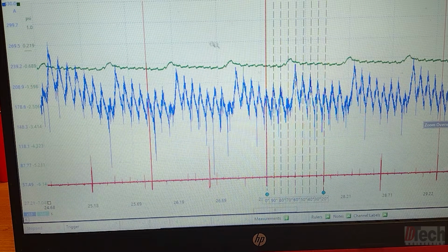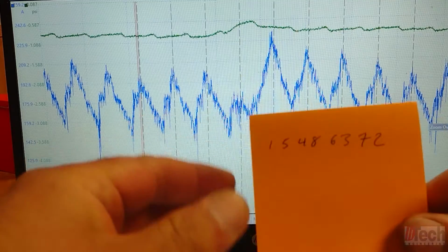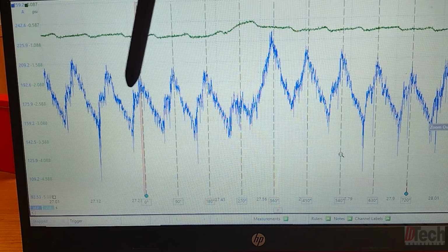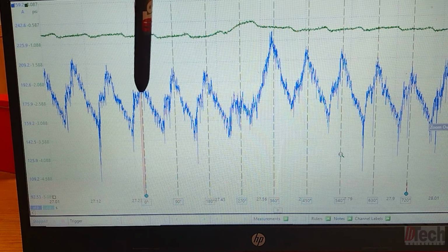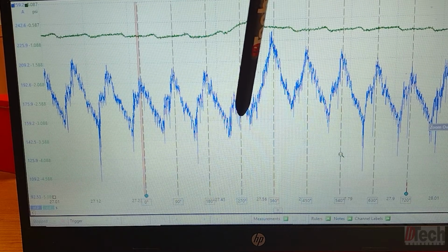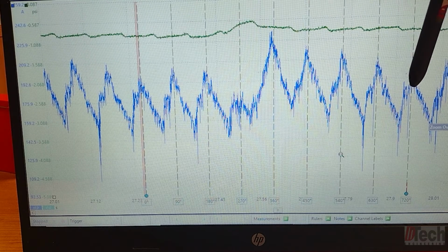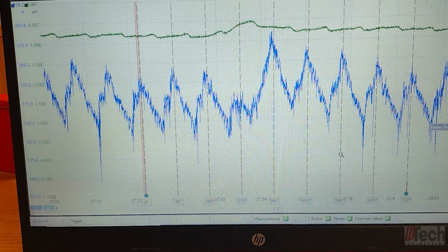As far as identifying which cylinder is the low cylinder, if we take a look at what our firing order is, it's 1-5-4-8-6-3-7-2. If we apply that here from ignition 1 back to ignition 1, our firing order is 1-5-4-8-6-3-7-2 back to 1. So our suspect or faulty low compression cylinder is number 8. Around that time also is where we see the anomaly on the intake trace.